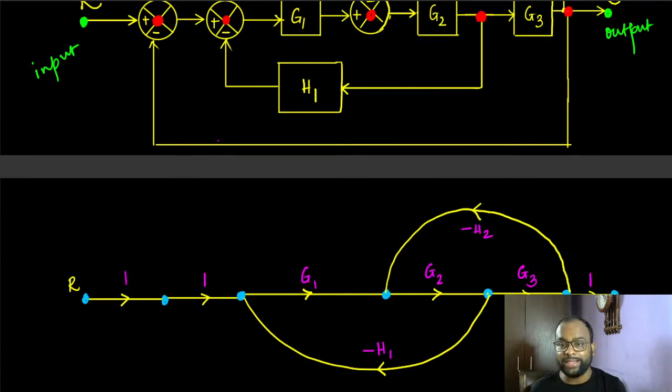But in order to avoid that, we compensate for the additional required energy through an op amp, through a buffer. Okay. Op amp based buffer. The buffer does not amplify the signal. It only makes sure that whatever load I have connected is supplied with the proper voltage. Load means current, in electrical engineering terminology. Higher load means higher current being drawn. So whatever current is being drawn gets satisfied through the application of a buffer.